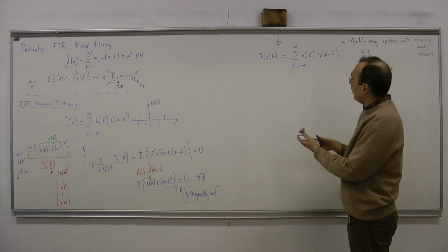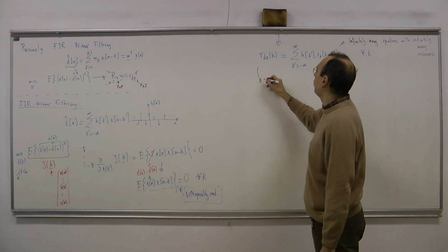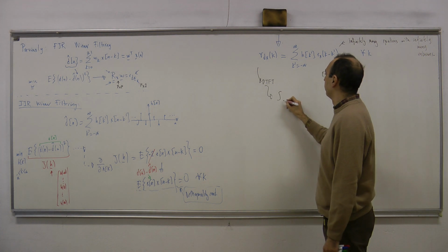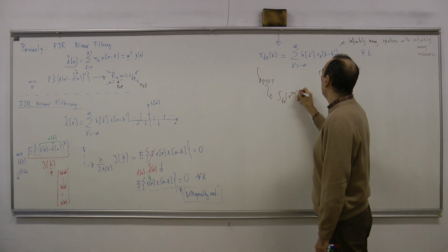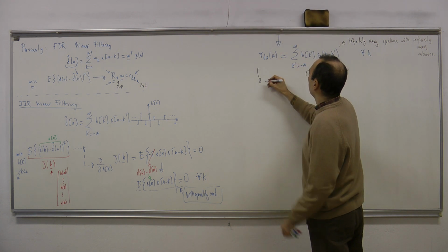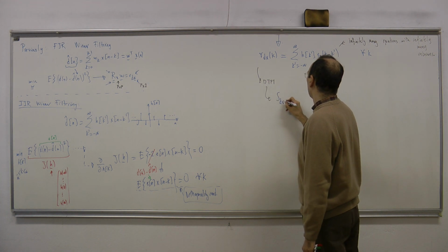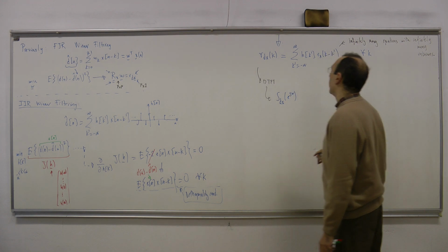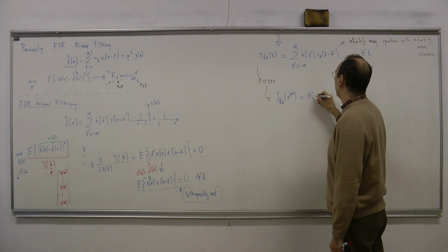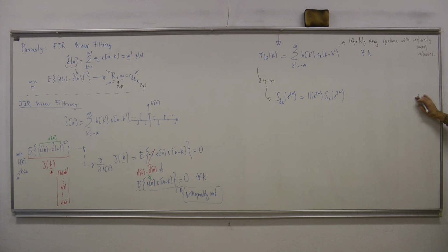Well, if you have some experience in signal processing, then immediately you would do the following. You would say, why not take the DTFT of this? Why? Well, we have defined this DTFT as S_dx(e^{jω}). But let me write this with blue. If I take this DTFT, okay, S_dx of e^{jω}. So about this one, this is H(e^{jω}) times S_x(e^{jω}).